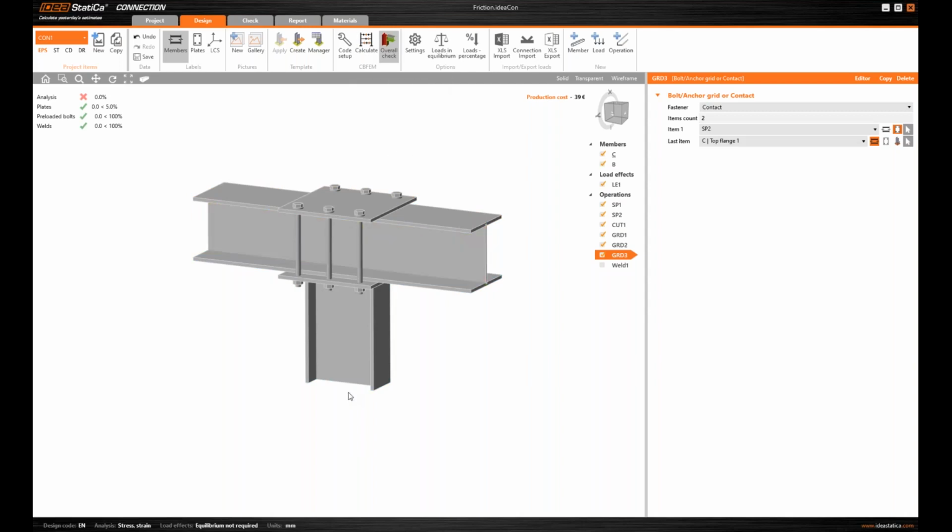Why is this happening? Since I have only the normal force, and I would assume this is really calculable. This is because by inducing the tension force to this connection, the connection is being deformed, and by the small deformations, there are very small shear forces and small moments generated as prying forces.